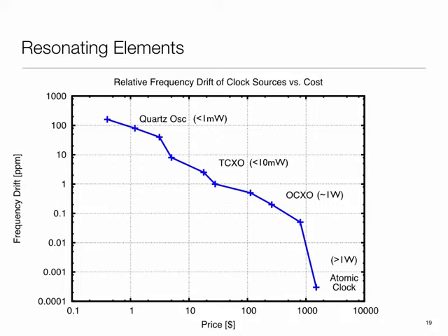Wait, are these power readings a continuous draw? These are the continuous draws. Now, that's a good point you're touching, which is if my system has to maintain the notion of time, then the oscillator has to keep running, in which case this penalty you will have to keep paying. Of course, the slower the clock frequency, the lower this number is going to be.